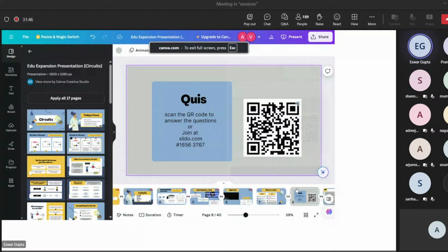What are the protocols essentially? That's what we intended to learn, right? What is SPI? What is I2C first? SPI features a single master and multiple slaves sharing one MISO and one MOSI line. The MOSI line splits into individual connections for each slave. A distinct chip select line is assigned to each slave, limiting the number of connectable slaves. So this sounds like some complicated English. I will break it down for you.